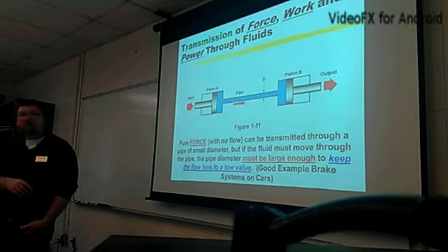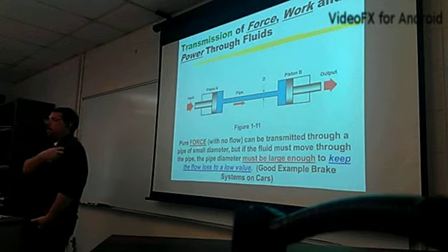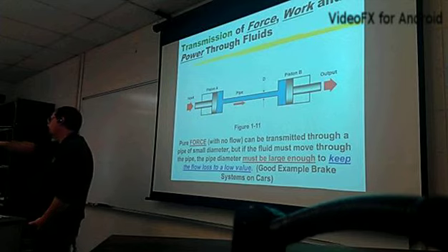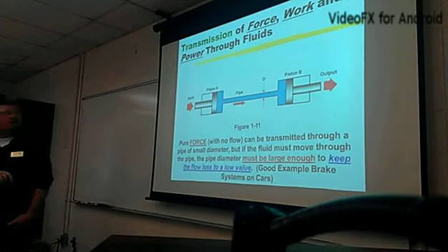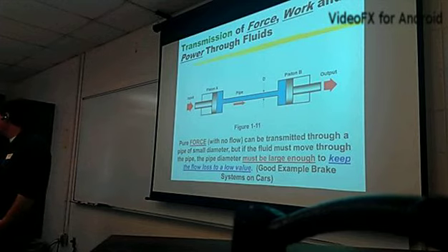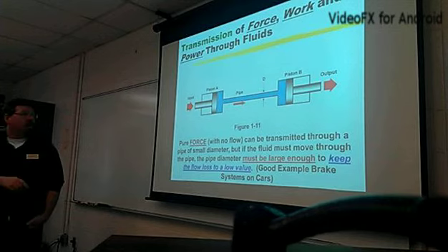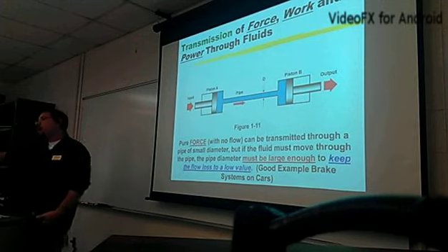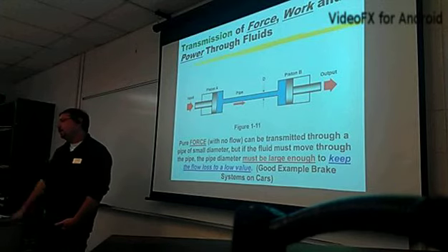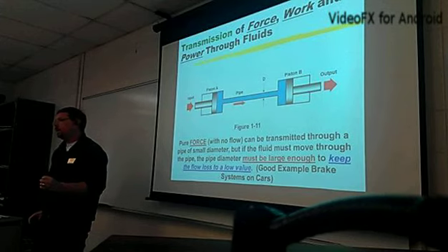Isn't that a Venturi there? Where you're constricting there at D? Kinda. Yeah, we're going to kind of demonstrate because I don't have a venturi. I wish I did, and it's hard for me to pull the pressure off. It's kind of a cobbled up mess when I do it, but you can see it a little bit. But there is a pressure loss right here because of that pipe. The longer the pipe, the smaller the pipe, we have a pressure loss in the hydraulic system.